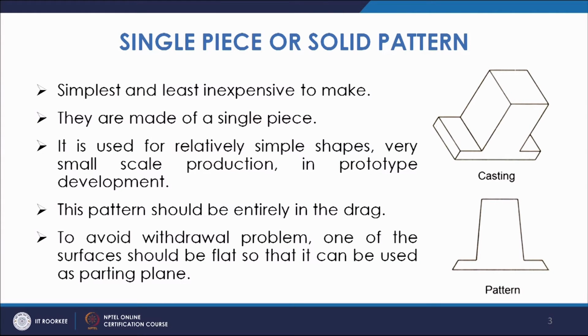It is simplest and least expensive to make, made of a single piece, used for relatively simple shapes, and it should be entirely in the drag, and you do not have any problem in withdrawing it. One of the surfaces has to be made flat, so that it can be used as parting plane and you can withdraw it.